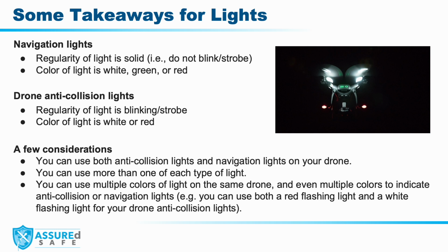Because the drone you are flying has not been certified as airworthy by the FAA, you will have to self-certify that your strobes are compliant. Manufacturers of anti-collision lights might say the strobes can be seen for a certain distance, like 3 statute miles, but you can't take their word for it since they have not been certified by the FAA as meeting the requirement. There is currently no process in place for anti-collision lights to be certified for drones. If you ever have an incident or accident, you will not want to tell the police, an insurance company, the FAA, the NTSB, a city attorney, or anyone else that you took the product packaging at face value. It's a good idea to confirm that your anti-collision lights meet the requirements.